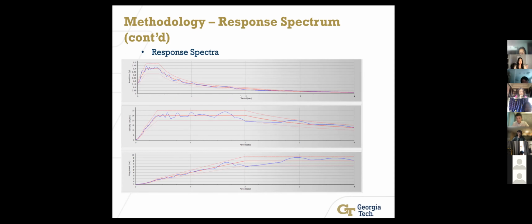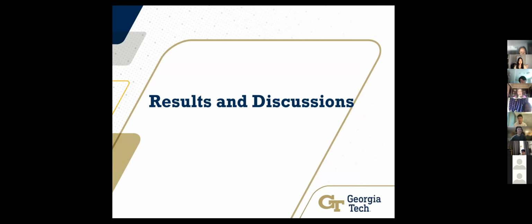And you can see here the dependent variable and the independent variable are not what we want, because if you want to insert this data into ANSYS, you have to have your x-axis in hertz and the y-axis in meters per second squared, and we just do the unit conversion in Excel.